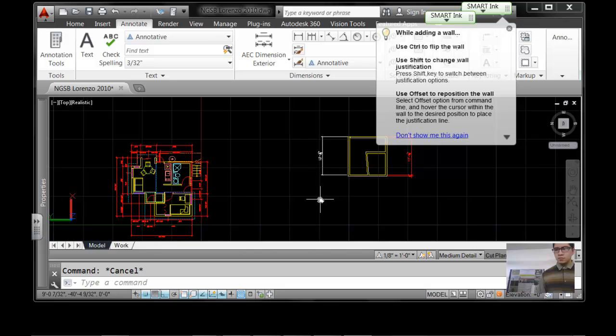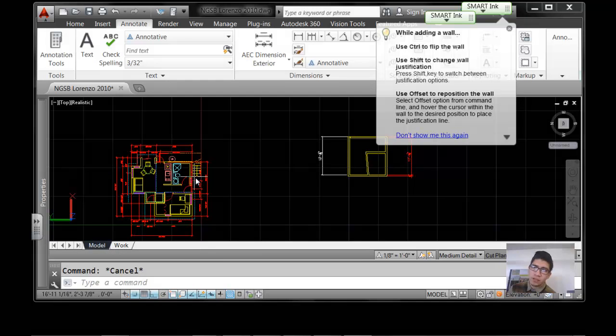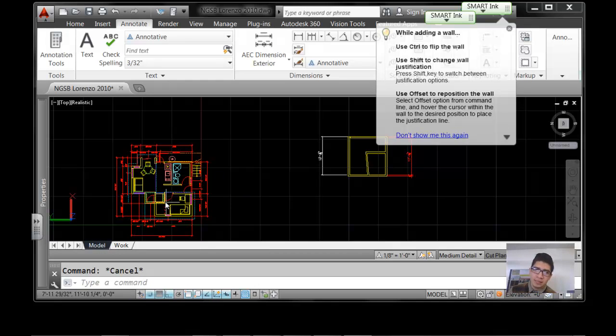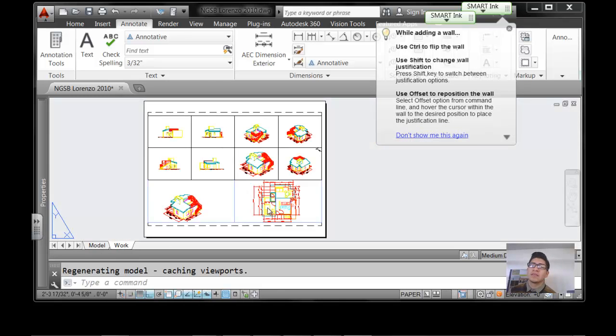So we're gonna learn about viewport, model, and then how to create a sheet for printing. All right, so this is model space, where this is real-time scale. So if a foot equals a foot, it's literally in lifetime. And paper space is where you could scale down. You could add a scale to, let's say, 1/4, and so you could print it on a paper. So in order to do that, you would want a title block.